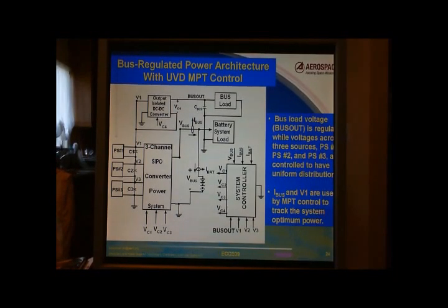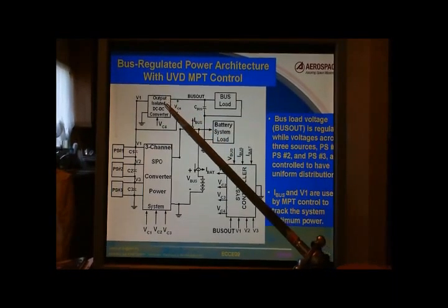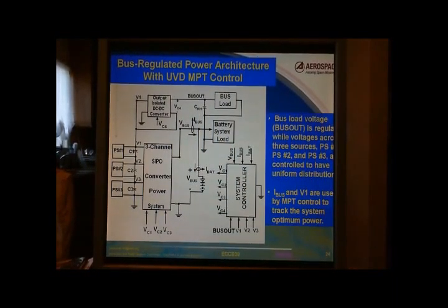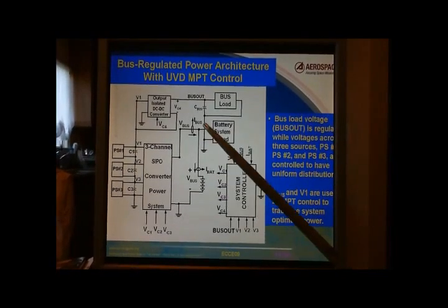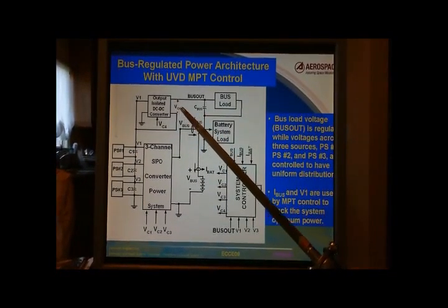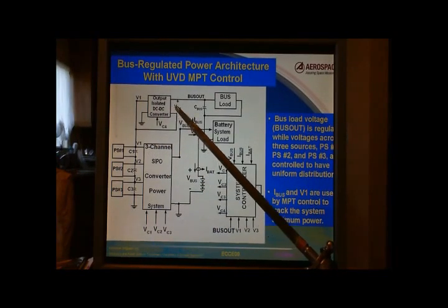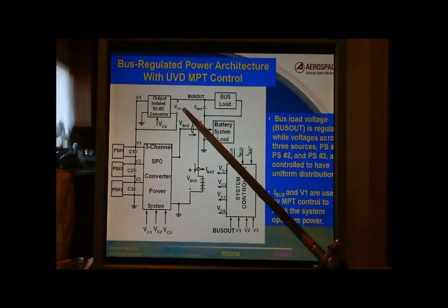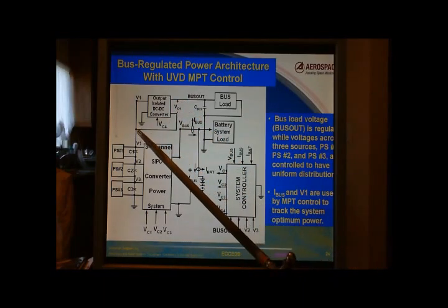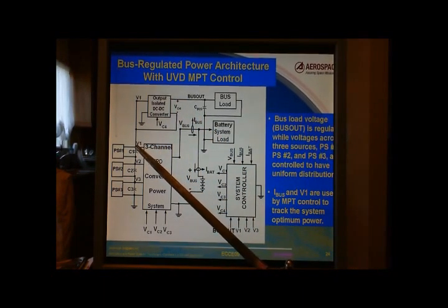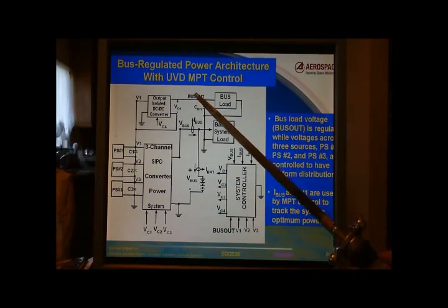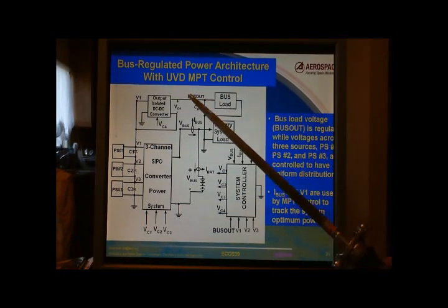In order to have the bus voltage regulated, the fourth converter, the output isolated DC converter, generates the output voltage VO4, which is only a small portion compared to the total serial input voltage V1. Superimposing this small output voltage VO4 on the total system serial input voltage produces the regulated bus voltage Bus Out.